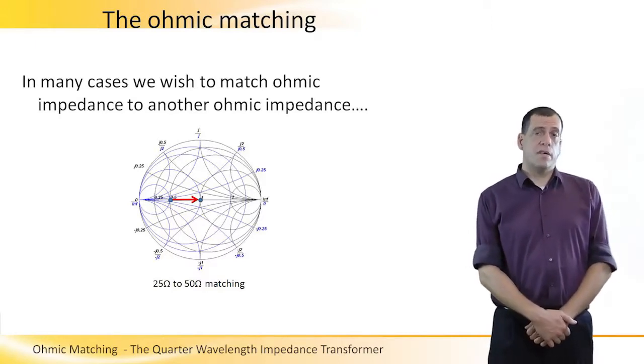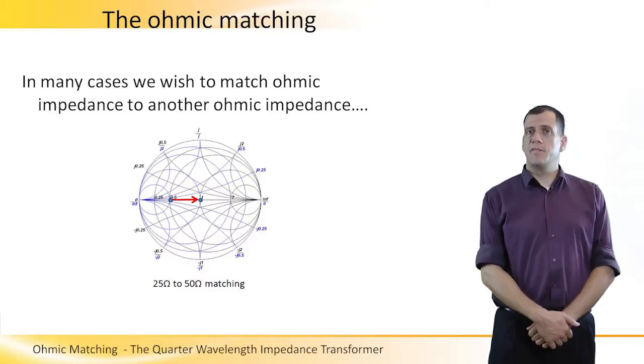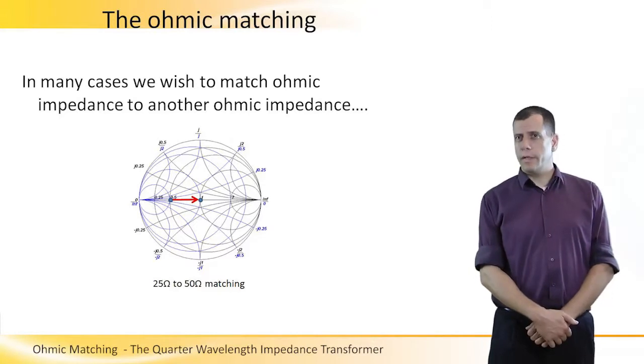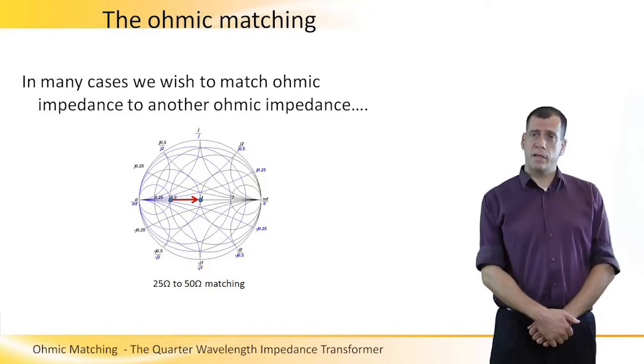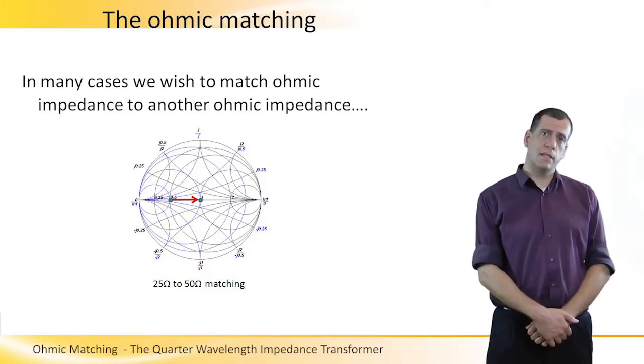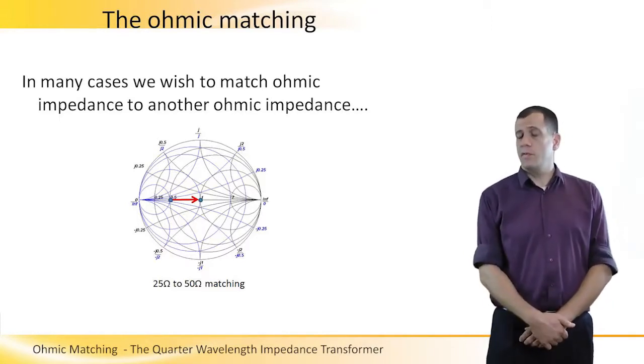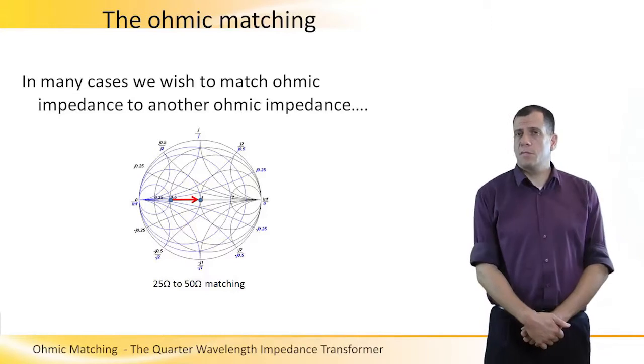There are some RFICs that have a different impedance than 50 ohm, like a 200 ohm differential, which is 100 ohm in relation to the ground, 100 in the positive terminal and 100 in the negative terminal. And differentially, this is 200. For example, it is possible also to have other types of impedances from devices.